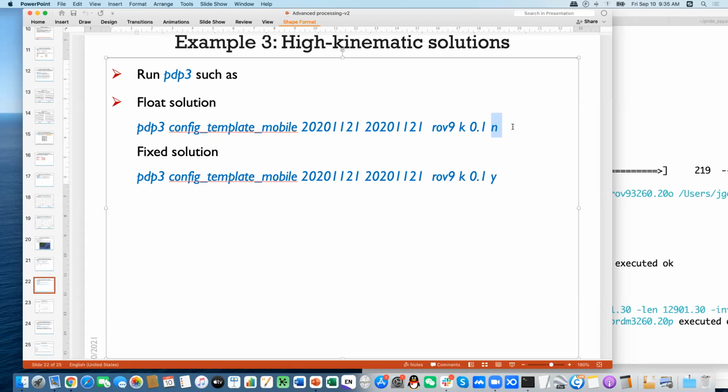In this case, the shaking of the antenna will cause some minor biases in your data processing. These biases cannot be recognized or processed by the software, and actually cannot be processed by any software because they are unknown. Such biases are non-integer biases, so they will be assimilated into the ambiguities, destroying their integer properties.